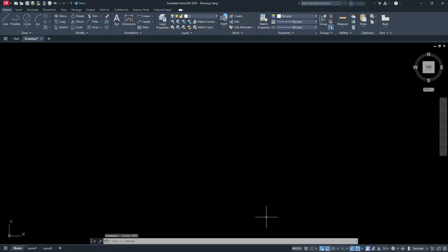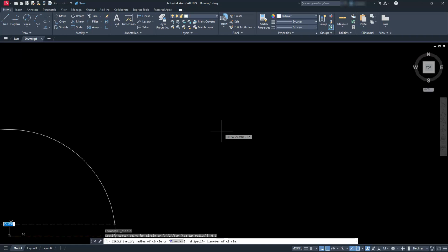All right, the first thing I'm going to do is create a big circle with a diameter, right? I'm going to create that top view. So let's choose a circle, center diameter. I'm going to place this one at the origin, so I'll just type in 0, 0. Go ahead and hit enter. And now the diameter of this super large circle will be 120.